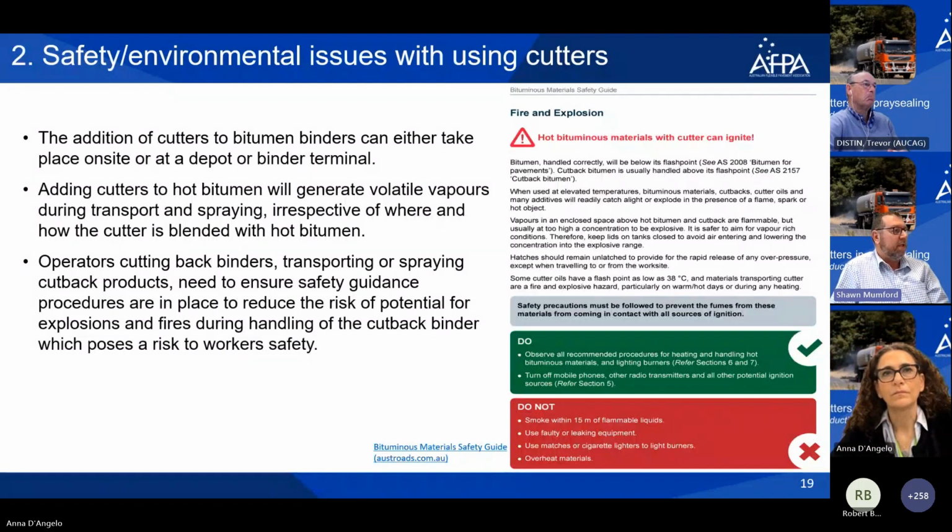Operators that are using cutback binders or cutting back the binders in the field, transporting or spraying those products, need to ensure that safety guidance procedures are in place to reduce the risk and potential for those explosions and fires during the handling of the cutback binder process.